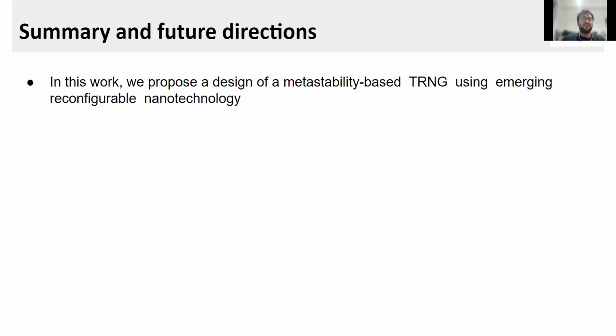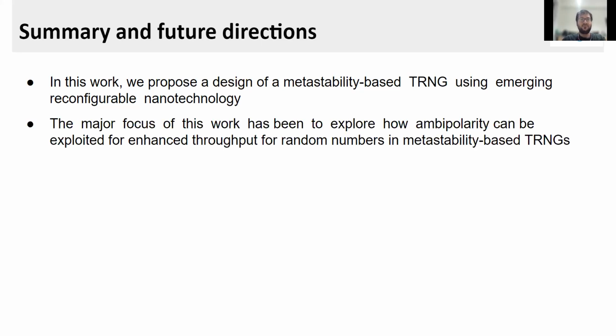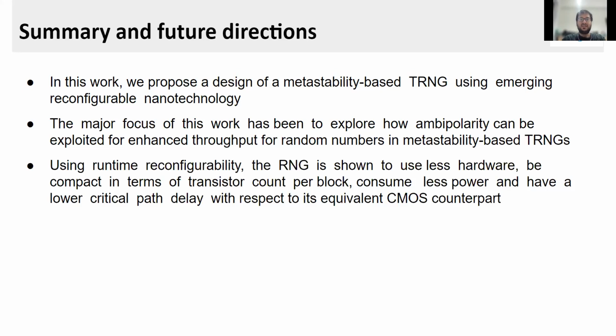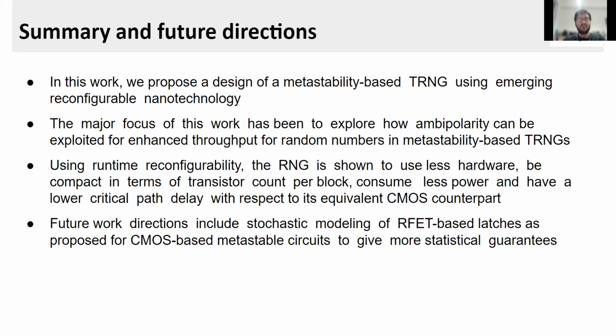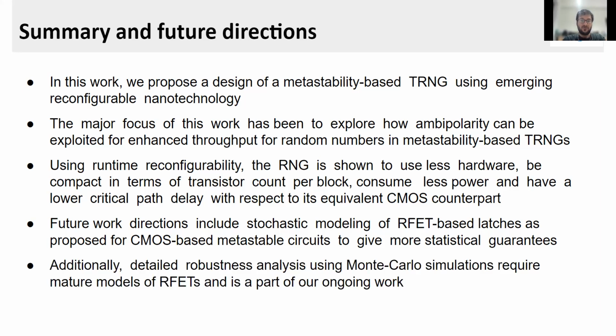So in this work, we propose the design of a metastability-based true random number generator using emerging reconfigurable nanotechnology. The major focus of this work has been to explore how ambipolarity can be exploited for enhanced throughput for random number generation. Using runtime reconfiguration, the RNG is shown to use less hardware, be compact in terms of transistor count, consume less power, and have a low critical path delay as compared to the CMOS equivalent. Future work includes stochastic modeling of the RFET-based latches as proposed for the CMOS-based metastable circuit, followed by Monte Carlo simulations to show PVT robustness.